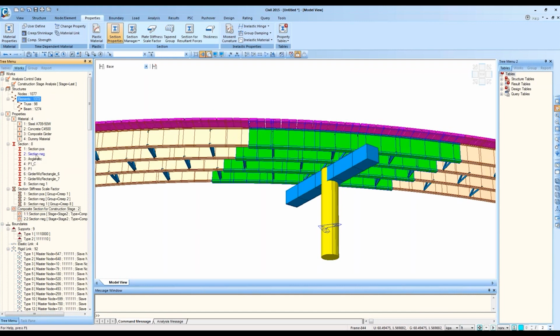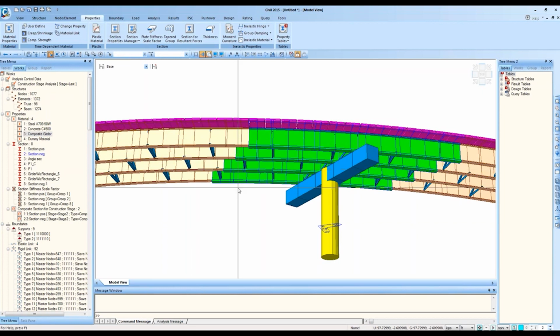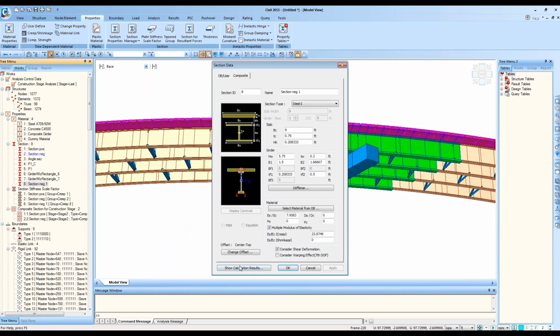All I need to do is select those sections using the section property or material ID or using the selection tools, whatever the case may be, and drag and drop the new property that you want to apply. So this is one way of modifying, and also you don't always have to define something new and apply it again. You can simply modify within the wizard too.